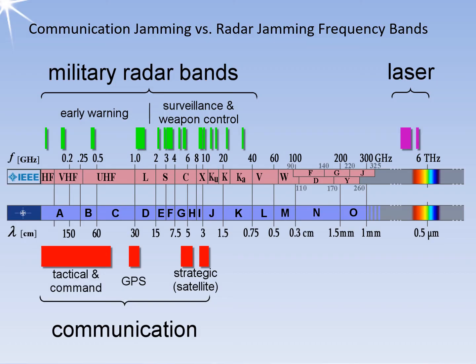Jamming signals can be categorized into radar signals and communication signals. The primary difference between radar and communication jamming is in the geometry. Despite their different purposes, these two types of jamming signals can share similar parameters. Radar signals can be either pulsed or continuous, while communication signals are mostly continuous. Radar signals are generally in the microwave frequency range but can also be in the low or high VHF range and can even extend into the millimeter range.